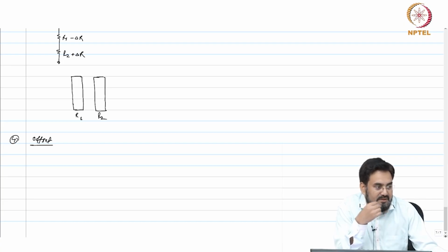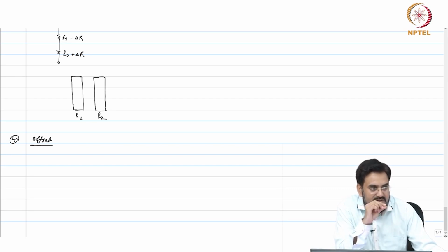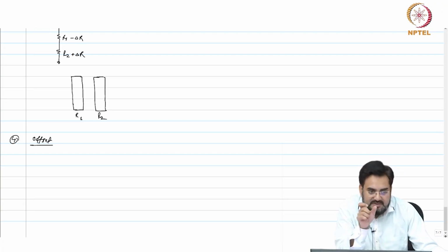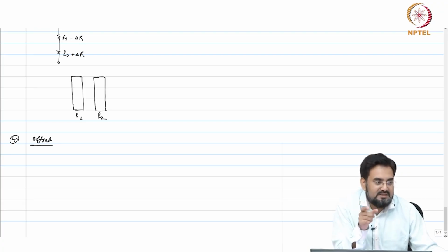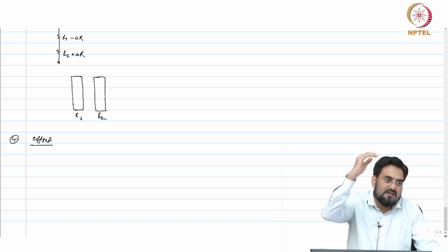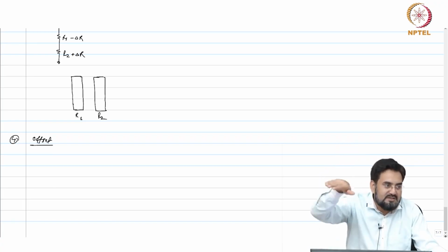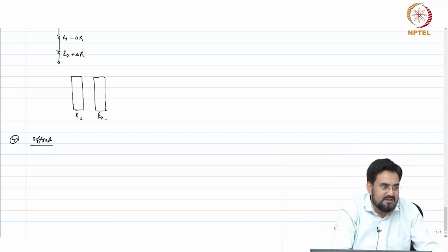So if you are not giving any input, meaning not giving any differential input, so when you short the two inputs, the differential input is 0 and you expect a 0 output. Okay. So 0 output, in terms of 0 volt, corresponds to when you have a plus VDD and minus VDD. But if you have a ground and VDD, then you expect to settle at a mid voltage. Okay, that will correspond to your 0 output in that case.